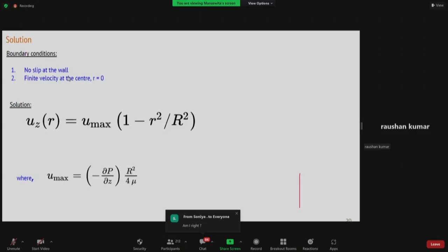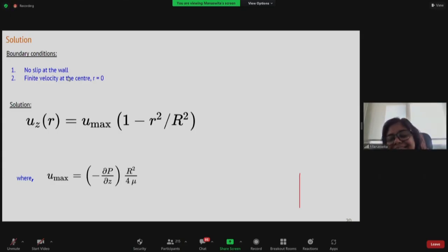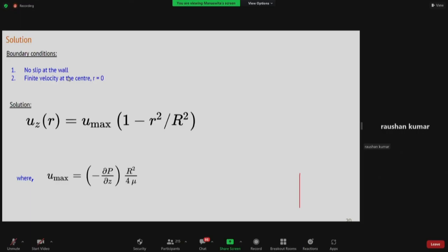Hello, ma'am. Thank you. Good morning, and thank you for your lecture. Ma'am, I am having one doubt. I have seen in Fluent that for boundary conditions, if we are simulating a constant density, incompressible flow, then velocity inlet and pressure outlet is the most common boundary condition. But for compressible flow, they prefer mass flow rate inlet at the inlet and mass flow rate outlet at the outlet.